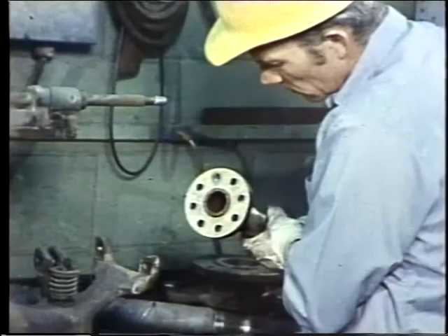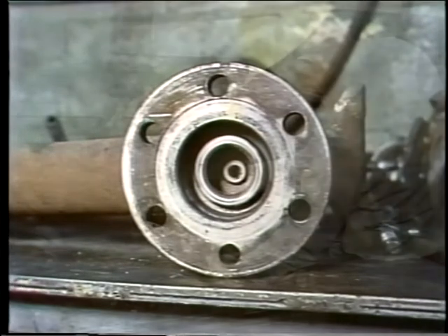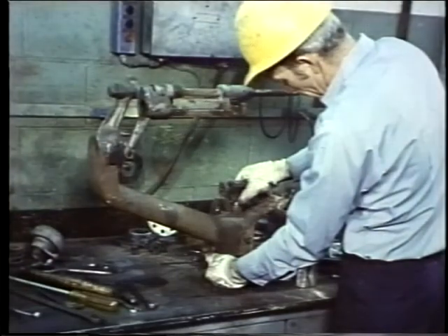At this point, it's appropriate to clean the gasket surface on the feed tube and the housing. On a soot blower of this type, the cast housing is called a gooseneck. In some instances, depending on the age of the soot blower, it may be time now to send the casting to be X-ray tested to make sure there are no hidden cracks in the casting that could lead to failure. When inspection is complete, the soot blower is ready to go back together.